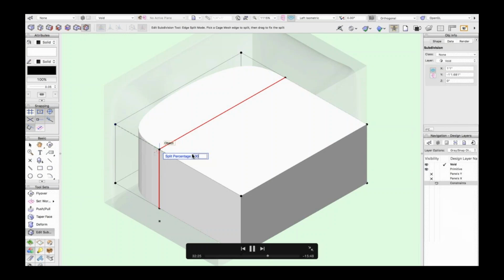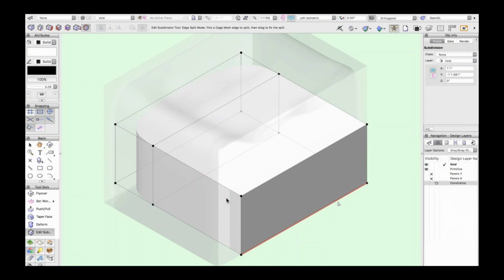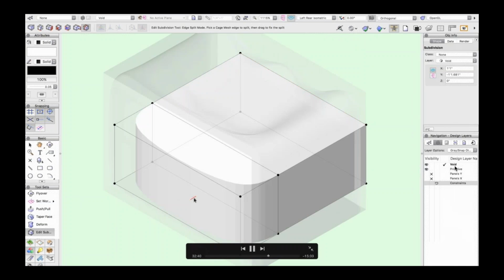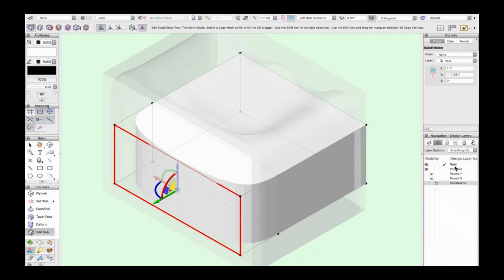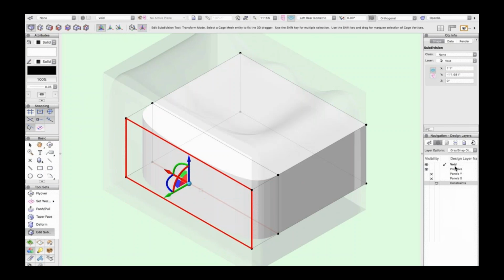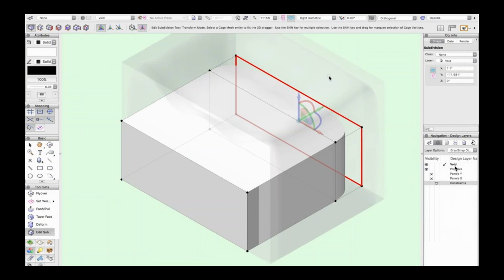Okay, so this is actually the correction of that, and now I'm using another subdivision object. I've created a design layer here on the right-hand side. You see I've called it void. So I'm creating the object that's going to inform the void that is going to be subtracted from that original bench form. The reason why I'm using this subdivision object is that it gives me the ability to give it a nice, smooth, free-form shape that goes along with the bench itself.